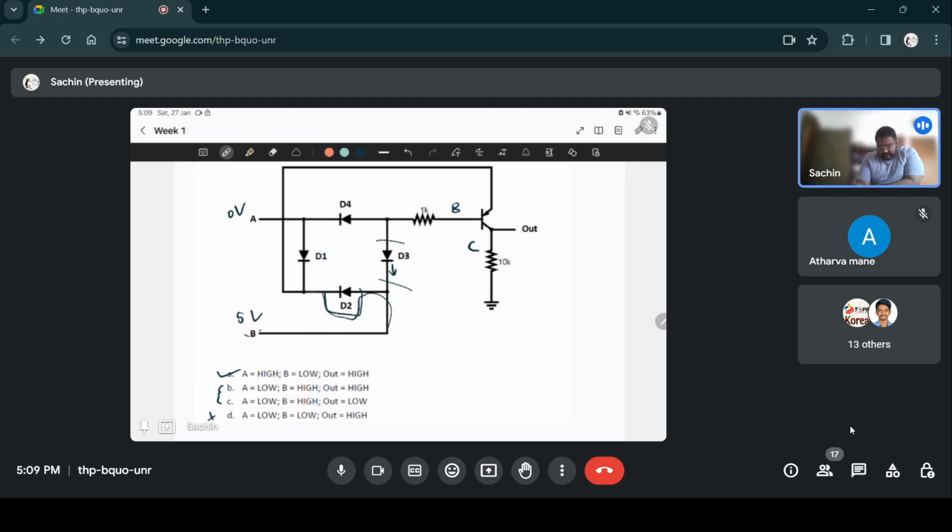So this again is connected to the emitter, you can see. So again the emitter is at 5 volts, just through a different path. And since this is at 0 volts, this will be reverse biased, and this will bring this voltage down to 0 volts. Similar to how in the previous case D3 brought this voltage to 0 volts, here D4 will bring it to 0 volts.